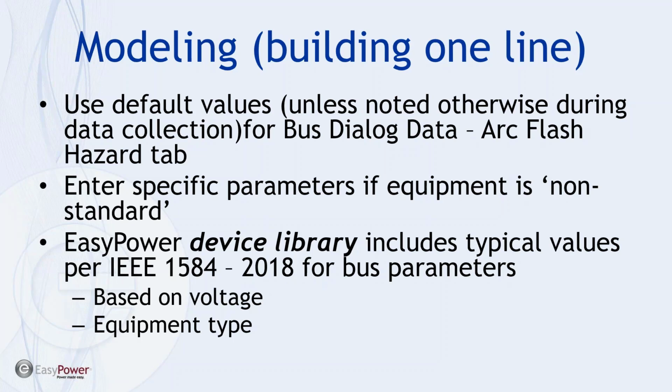And you'll see when we get into the tools that the bus dialog makes it relatively easy on an individual bus basis with the arc flash hazard tab itself. And you only need to enter non-standard parameters if the equipment has been identified as such. Just as a point of note, and we'll touch on this when we get into the tools, the device library includes all the typical values that are recommended in 1584, and you can verify these, and these are the values that are brought up when you start to model the bus work.